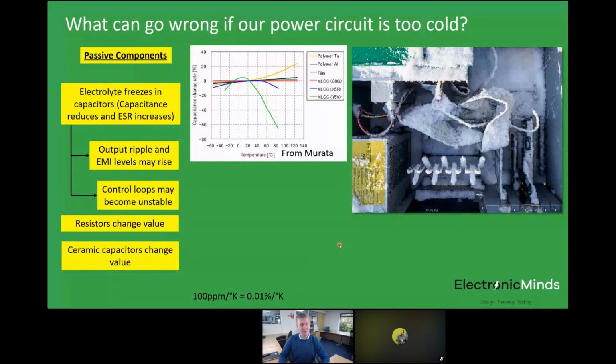Ceramic capacitors, depending on the grade of the ceramic material, can change massively, and you have to be really careful. And you can see certain ceramic capacitors are available that seem to have a hugely high energy density capability, but they tend to be the ones with this Y5V characteristic. And I wouldn't really advocate using that sort of a dielectric for power electronics, because look at the variation you get in capacitance over temperature for a Y5V. It's huge. If you need a really stable capacitor with temperature, then you need the C0G type characteristic here, which has an almost flat characteristic.